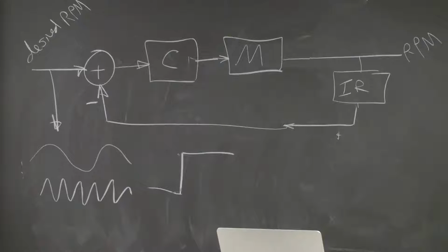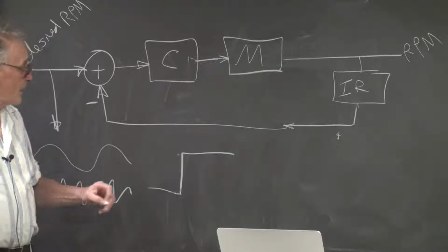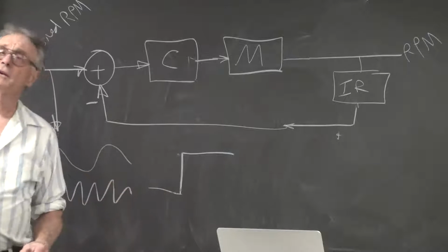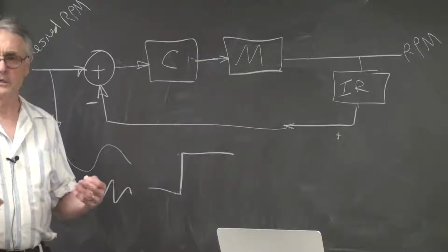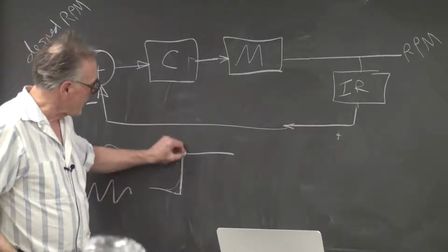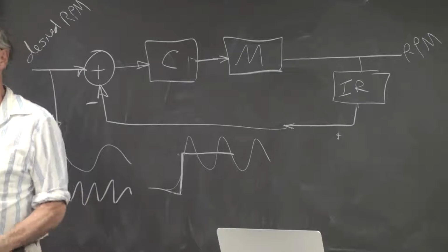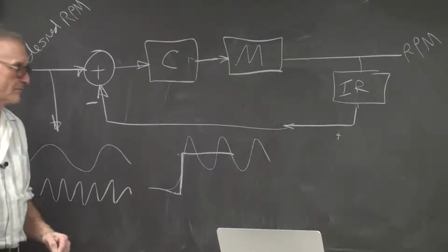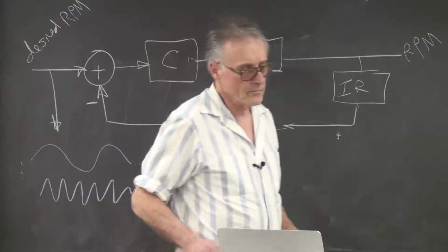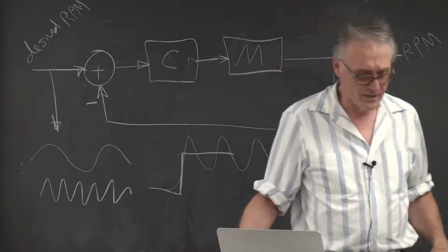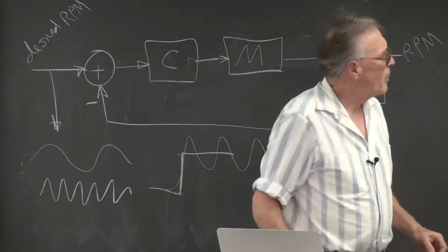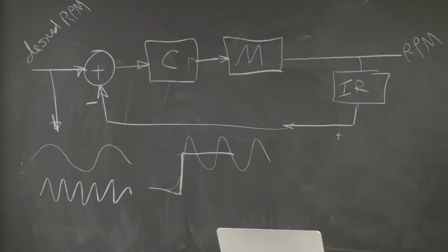That's not good, because now the error is amplified rather than being suppressed. And what we'll find is that if you get a phase shift near 180 degrees, the system is going to oscillate and will never stabilize. But let's now go back and do some analysis. Oh, I guess we should say, all right, so this is a second order system.